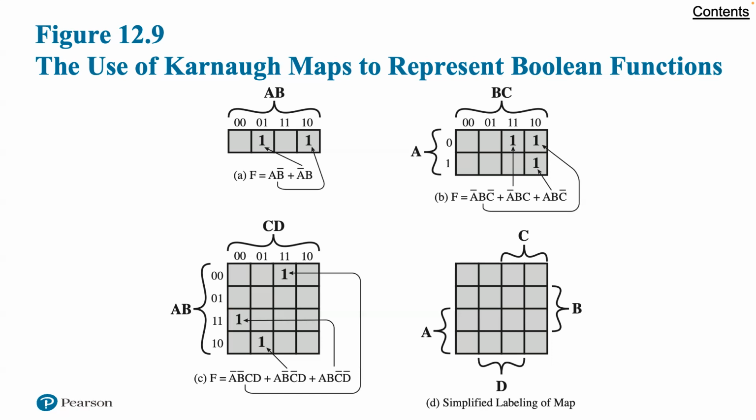Figure 12.9b shows the results for the truth table of table 12.4. To convert from a Boolean expression to a map, it is first necessary to put the expression into what is referred to as the canonical form. Each term in the expression must contain each variable. So, for example, if we have equation 12.3, we must first expand it into the full form of equation 12.1 and then convert this into a map.